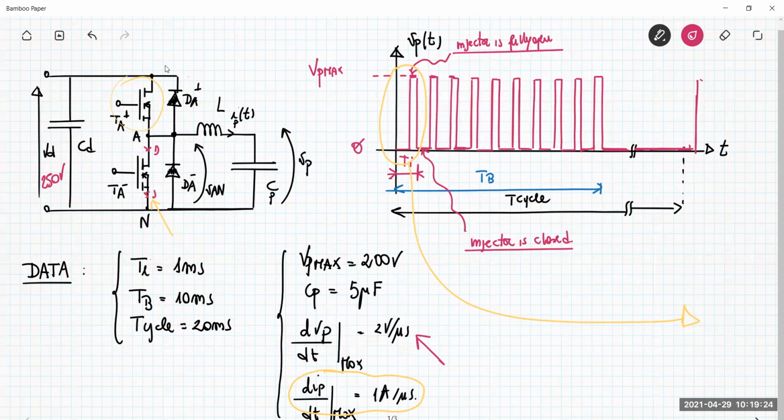Okay, so this voltage must not lead the transistor into the breakdown region. So you have to choose a transistor with a breakdown voltage which is higher than 250, of course. For example, 300 volts. Okay, if you choose not 250, but, I don't know, 600 volts, maybe it's difficult to find a MOSFET having a very low Rds on resistance with a breakdown voltage higher than 600 volts.